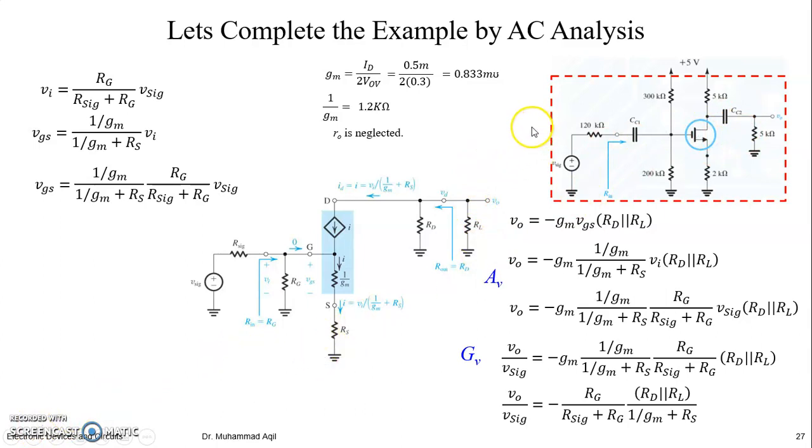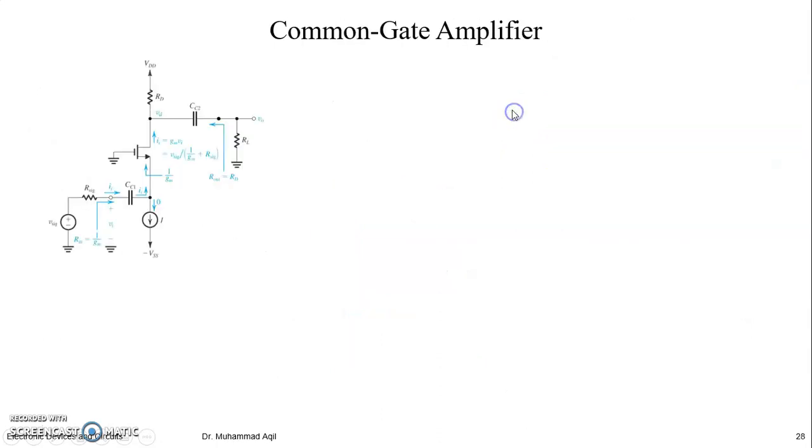Okay, so now we can go to the remaining discrete circuit amplifiers, the common gate and common drain amplifiers. The common gate amplifier has a relation in which the AC signal will see a ground or common terminal at the gate, and the signal is applied at the source, right? Because if the drain is available, it will prefer to be the output terminal, right? So then the source will compromise as the emitter does in BJTs.